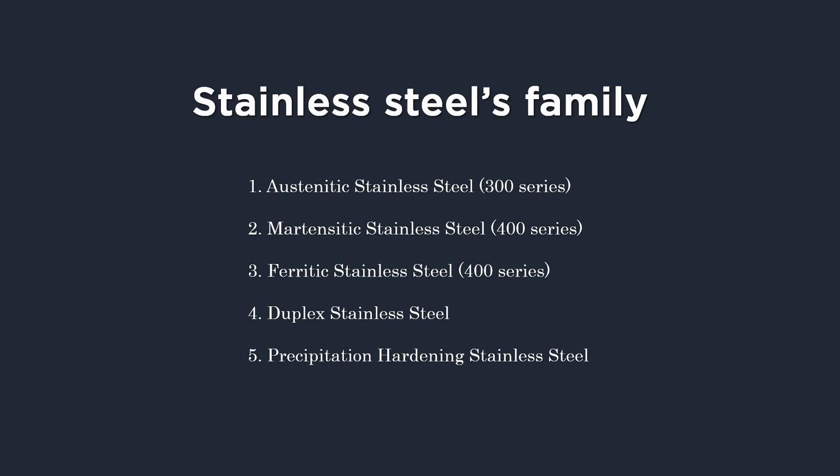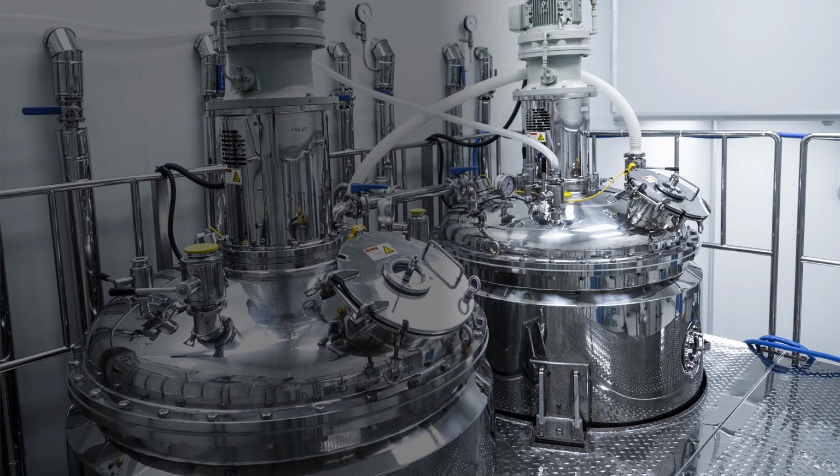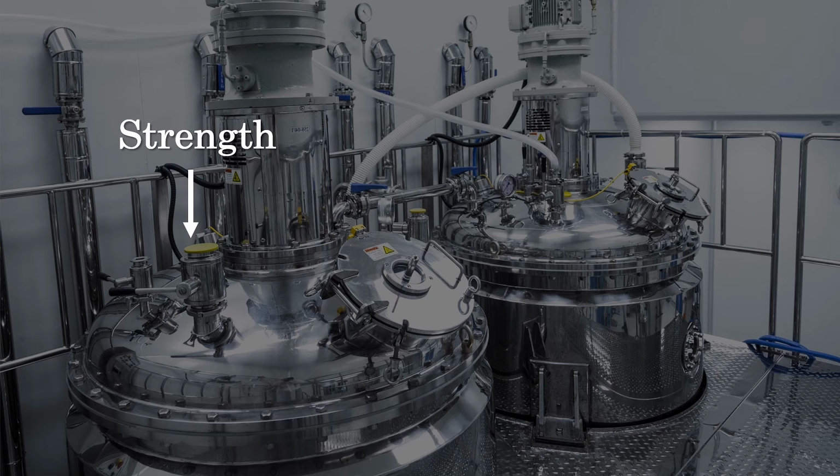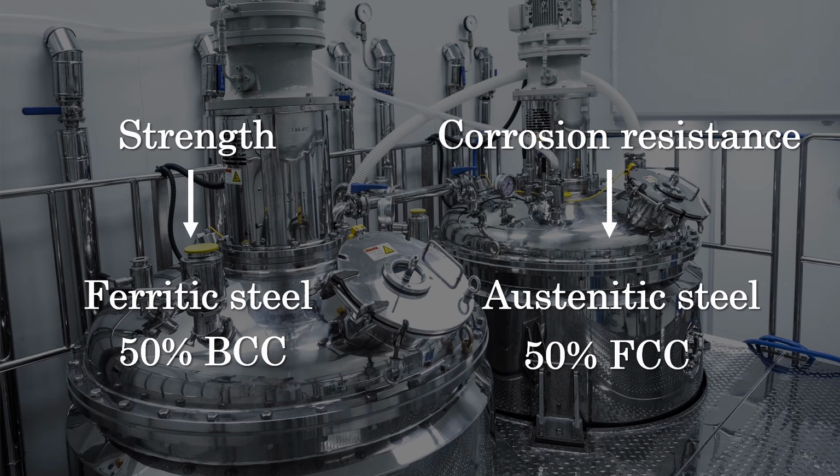Now we are moving to premium stainless steel, the duplex stainless steel. These stainless steels combine the best of both, the strength of ferritic stainless steel and the corrosion resistance of austenitic stainless steel. So their crystal structure is 50% FCC and 50% BCC.